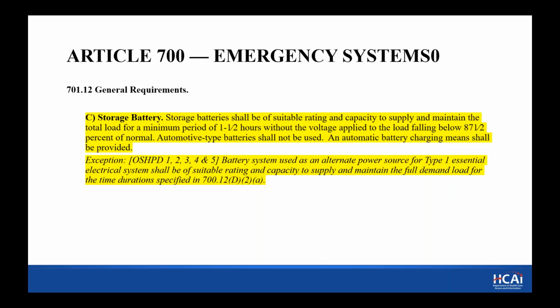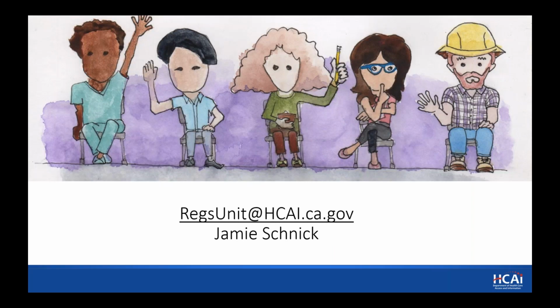Storage batteries, we've identified they can be part of the emergency system, and here in 700 we're just reiterating that the sizing and the rating would need to meet the duration specified in 712D, which we discussed. And that concludes my presentation. I'm going to go ahead and open it up for questions.